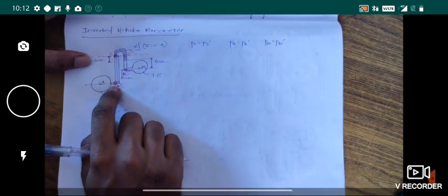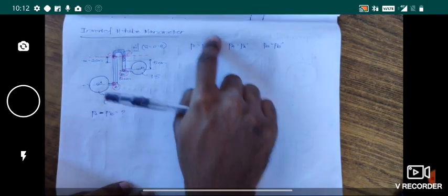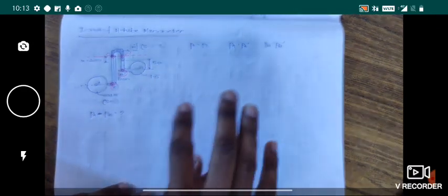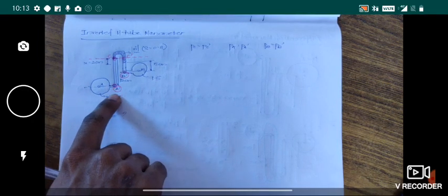Now how to write the pressure at PA dash? This is a step. Earlier what we had written is that we'll directly take this equation and write the equation for PC and PC dash. But here, since it is an inverted U-tube manometer, you take this point PA dash.